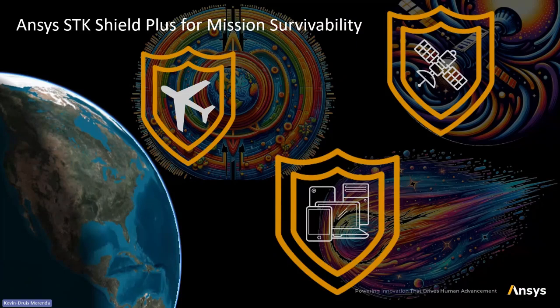So it's used to be able to understand the threat, but if you are worried about the frequency content, at that point we would just scale the frequency response that we get from the shielding effectiveness analysis to the threat environment that you simulated in the other module in STK.